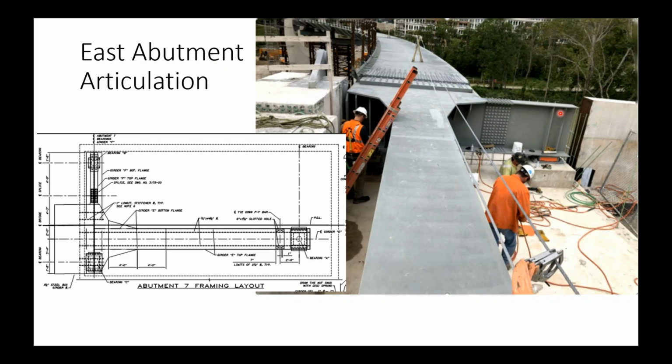We've made the beam much wider than this triangular steel box, and that allowed us to give a nice wide base to put the bearings, take out that torsion with a nice stable platform. So this outrigger beam here is actually 14 feet wide, so the eventual concrete deck will be the full width of this beam. But it gives us a nice stable platform to put these bearings on.